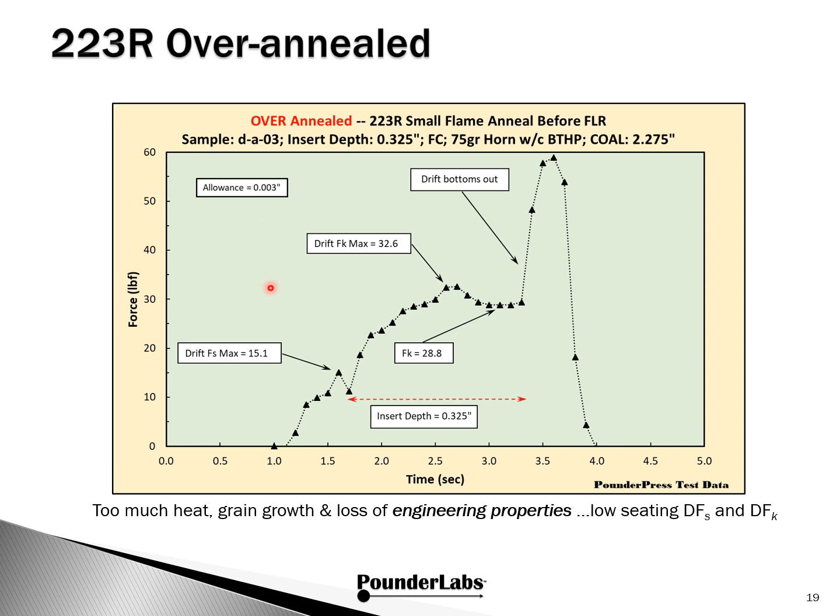But what's happened, we've had too much heat for too long, and this creates grain growth in the brass. In the material sciences discipline, this is called the loss of engineering property. For us specifically, we end up with a very, very soft gripping of the neck onto the bullet, which is an undesirable property. So here's a good clear example of what happens when you over anneal brass.